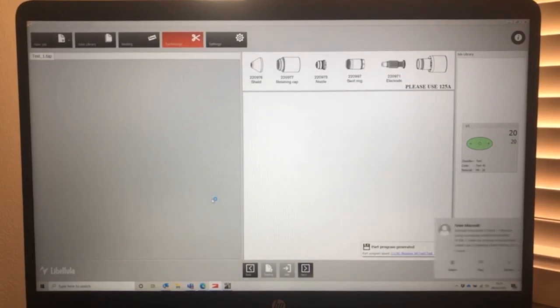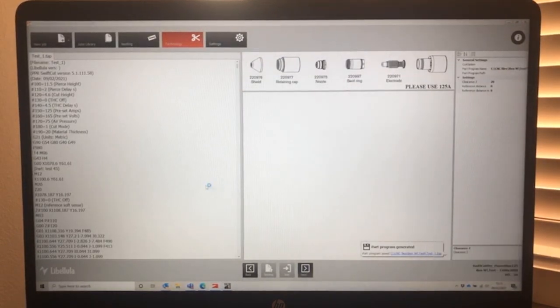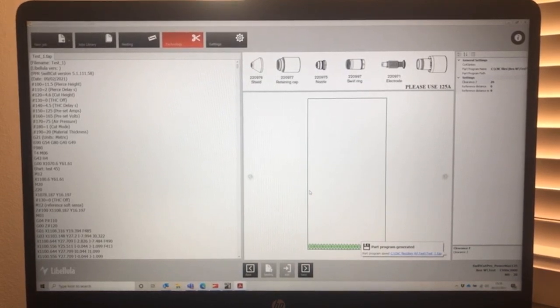So the next function brings you into the G-code creation. It's at this point really that you've completed creating the job, and you can see this by the part code generation logo with an icon that comes up at the bottom. On the left hand side you've got all of the details for the creation of the part itself. So that's the machine language and G-code that will be used to run the machine.